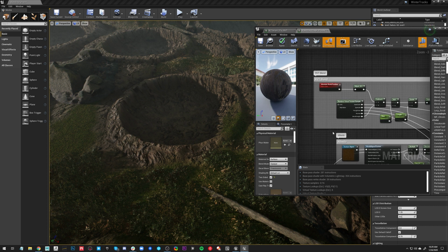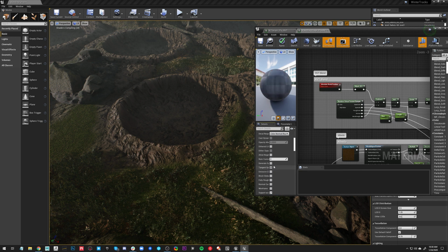Definitely. Gentlemen, I have a question for you from chat. Yes. Exile Mod would like to know if there's a reason why we're not blending with world space normals. We actually, I don't know if you mentioned that you need to disable tangent space normals, not material. Yeah, I actually did not mention that. Thank you for bringing that up. But in the creator material here, I actually had to disable tangent space normals. So if I actually enable that and just apply that again, you'll notice it doesn't look correct.